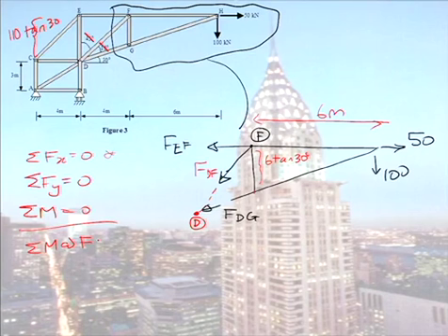So taking moments at F, and this is where people get confused, I have this force here, FDG, going off at an angle. So we know our moment is a force times a perpendicular distance, so I could work out that perpendicular distance in here, but I am likely to make an error because it's exam conditions. So what you can do is resolve this force FDG up into a sine component and its cos component.